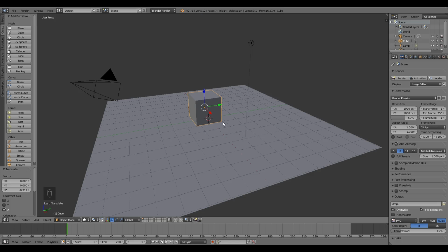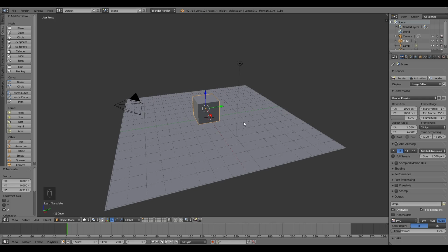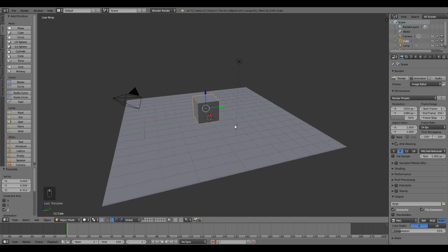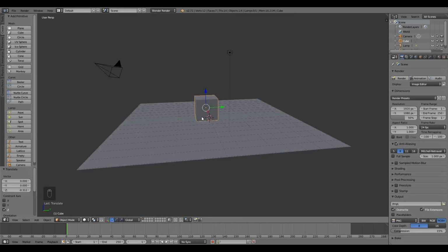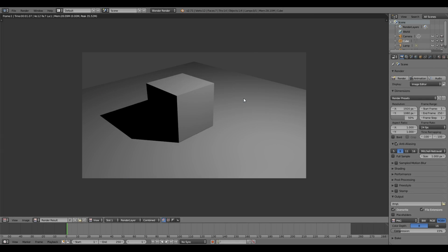Okay, now the next shortcut key, which is important, and you will get your first render out of this, is the F12 key. If we hit F12, it renders the scene. Render is just like another fancy word for making the end result. The quality you see right now is just like the construction graphics. We want to manipulate things and do whatever nerdy thing we desire. And then once we're happy with what we've made, we take a snapshot, like a camera, except the camera makes it look prettier. So hit F12 just to see what happens now.